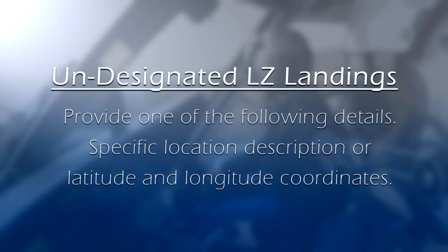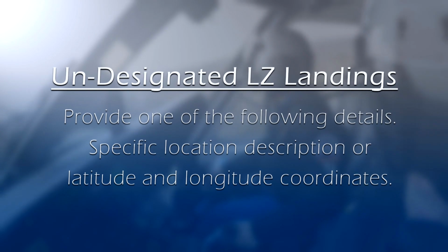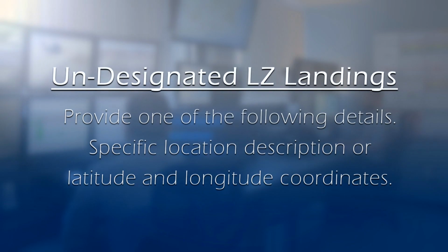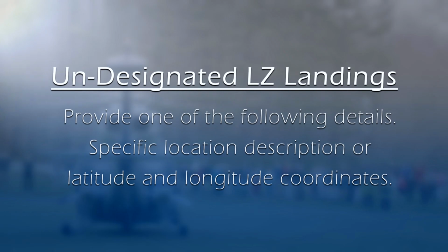If there is a need to land the helicopter in an undesignated LZ, such as a highway, provide the specific location description, for example, Route 495 South at exit 20, or provide the latitude and longitude coordinates.